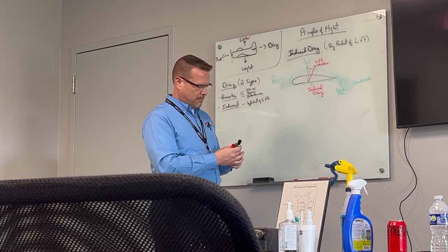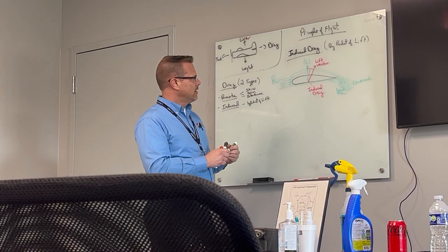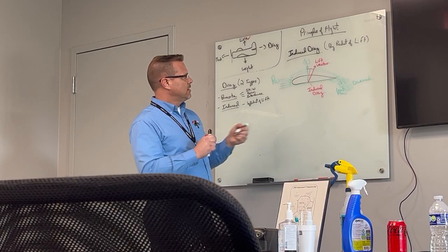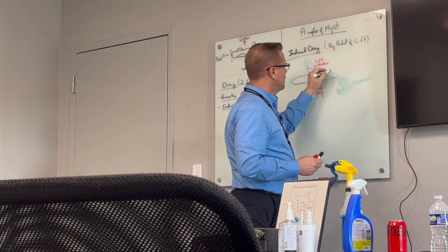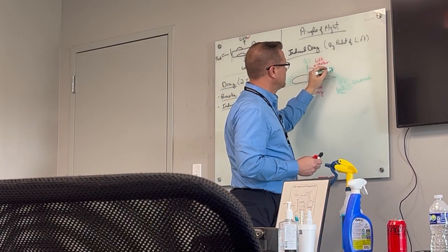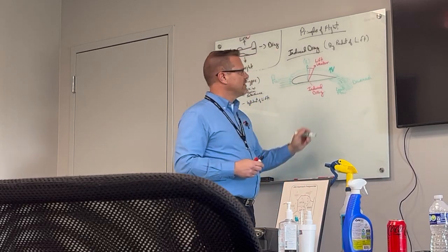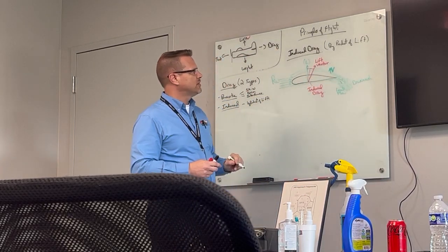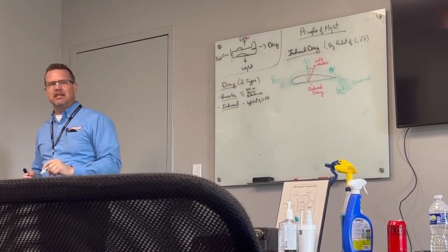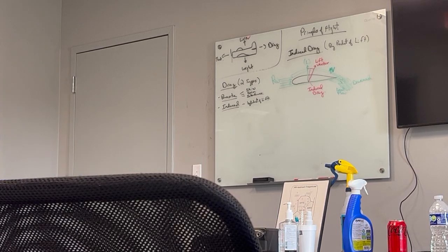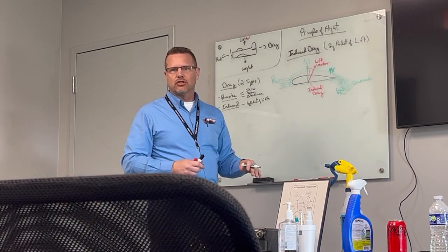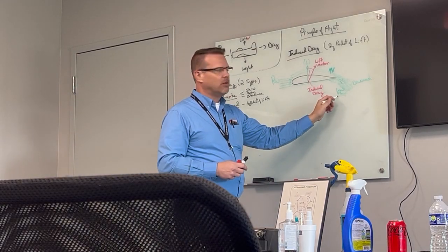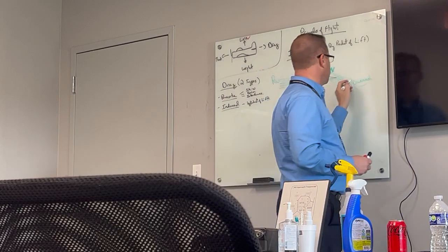we said that the air above the wing has a low pressure, but it also has a much higher velocity. That's why it has a lower pressure up there. Well, that air comes streaming off the top of that wing and comes slamming into the air that's just kind of slipping underneath the wing, and actually ends up redirecting the flow of air, kind of creating its own relative wind, and this is called the local flow, known as a downwash.